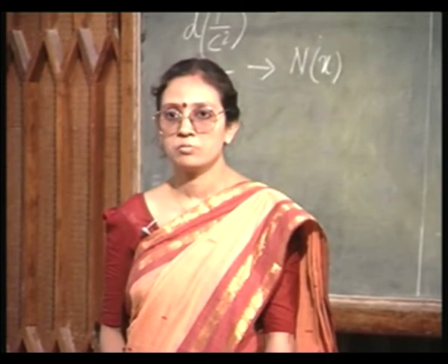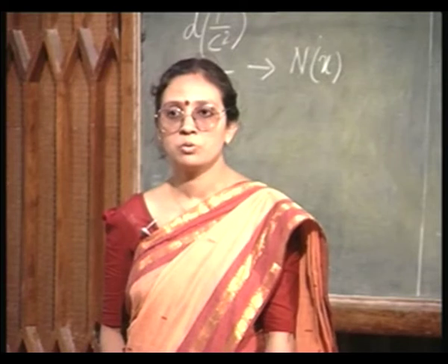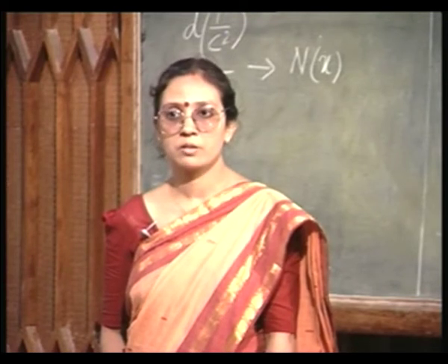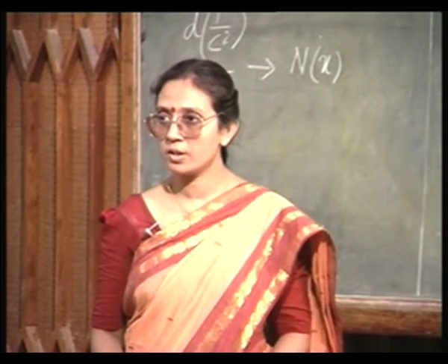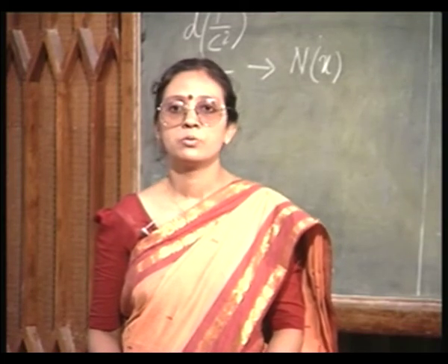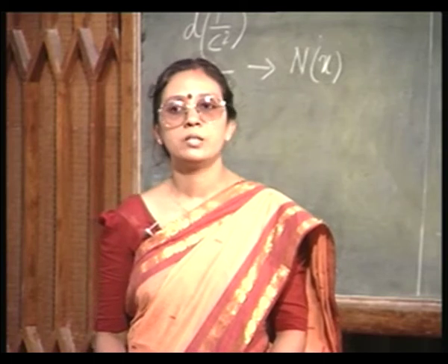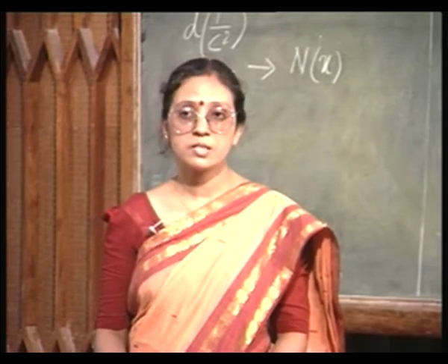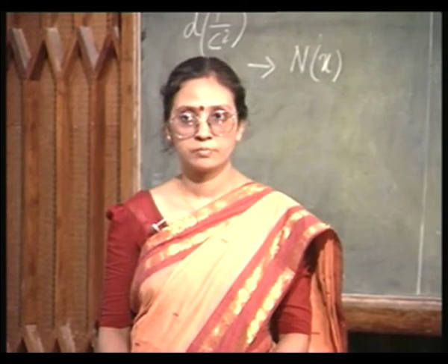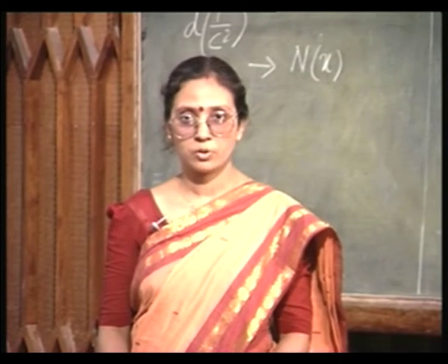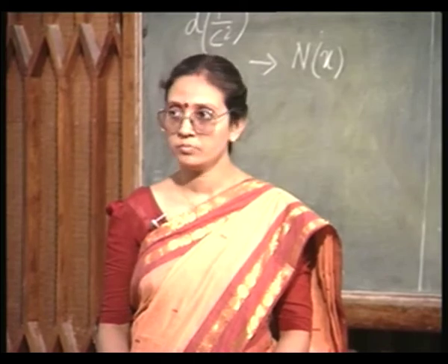So, you can measure the slope at points all over the depletion layer width, and you can find out how the doping profile is going to change. So, this is the CV technique of measuring the doping profile. Okay? We will stop here today.